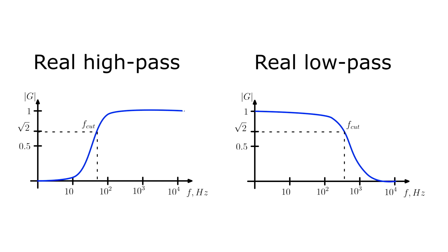The simplest filter, of the first order, has a sloped frequency response curve compared to the step function of an ideal filter. The point at which the signal is attenuated to 1/√2 times, or equally -3 dB, is the cutoff frequency point. The slope of the graph shows that the signal is attenuated twice per frequency doubling. Filters with a higher order have a steeper slope, resulting in a greater attenuation of frequencies above the cutoff point.